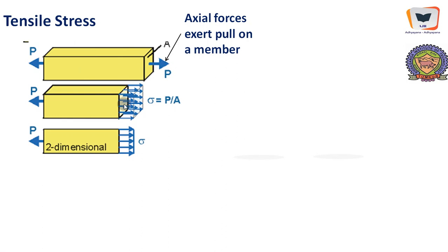However, when you take a section somewhere over here, you can see the stress coming into play, which is equal to P by A, and this is a three-dimensional view of the stress system. Anyway, we cannot write a three-dimensional stress system very easily, and our problem solving procedure will become cumbersome. Therefore throughout this particular course, we choose to write a two-dimensional stress system. That means here this particular line connotes the area of cross section.